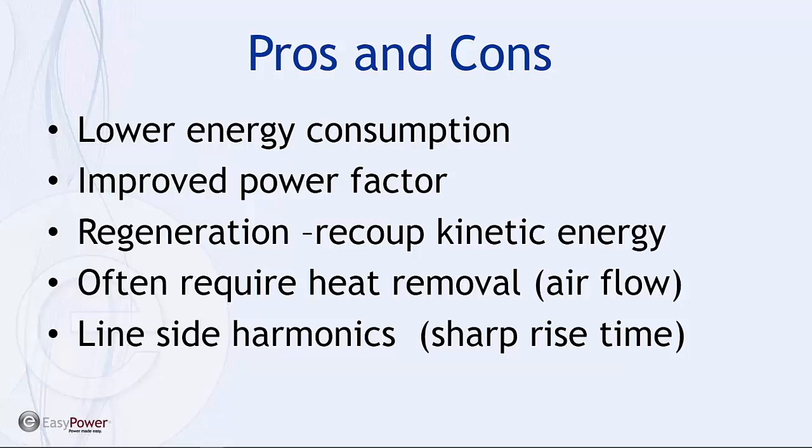First of all, on the pro side, they do in fact reduce the amount of energy consumed by a motor, especially when it's running at something less than full speed. And it does allow us to have much more finite precision in controlling the speed of the motor and regulating that speed with a little bit of a feedback loop.